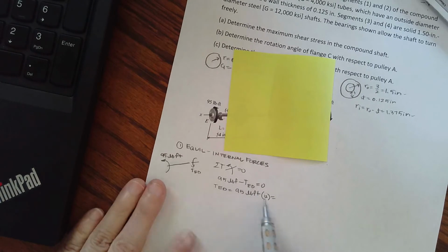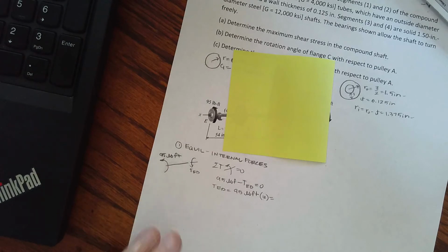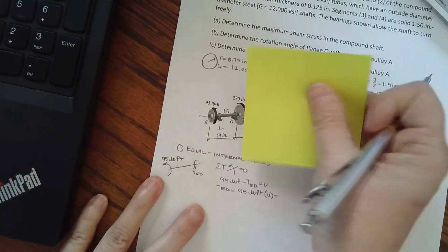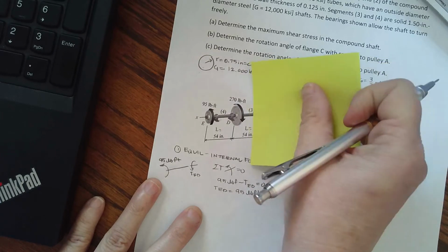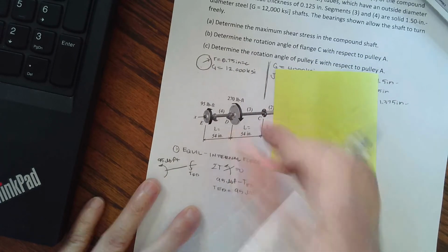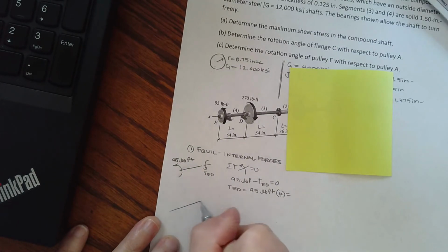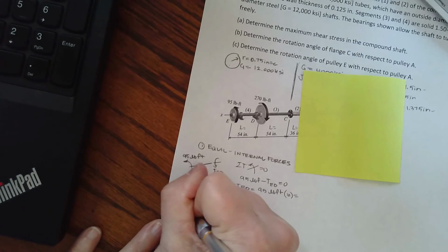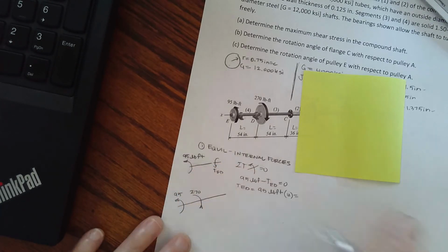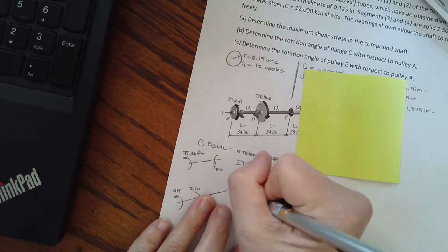And it makes sense that it's positive because if we're rotating there, we have to be coming back equal and opposite to keep us in equilibrium. So we're going to move our paper down, and we don't have a torque change till here. So both segments 3 and 2 will have the same internal torque. So again, I'm going to draw my free body diagram. I have 95 pound-feet. I have 270 pound-feet, and I can visually see which way this needs to go. But again, I'm going to assume positive.